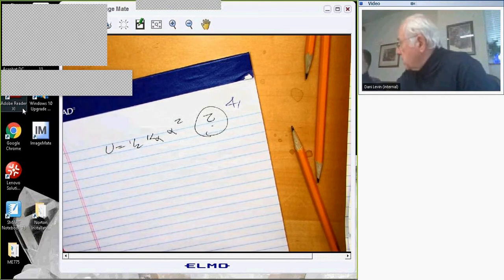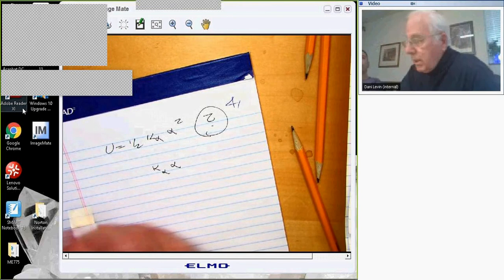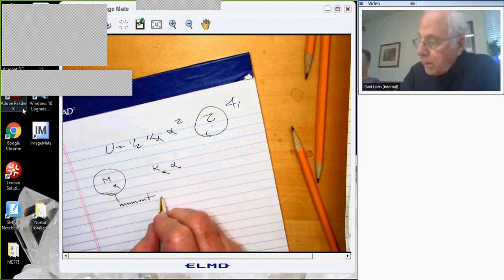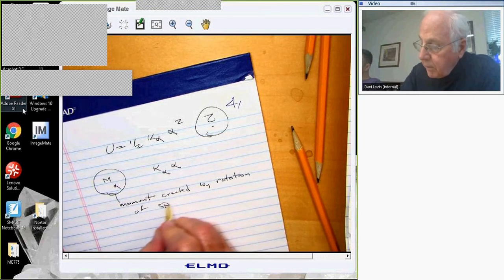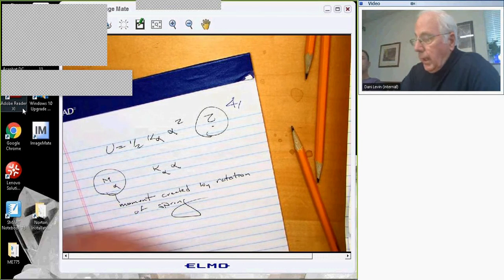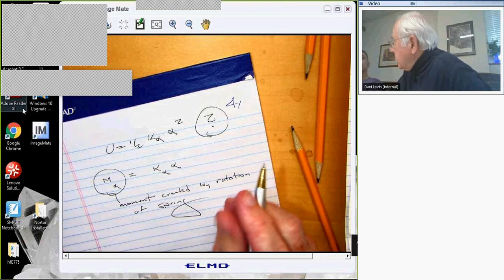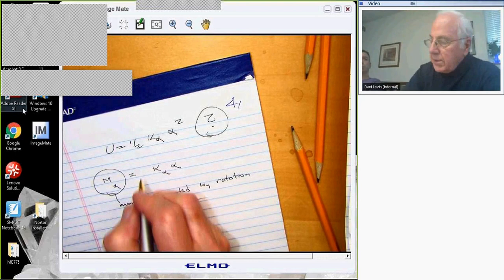the spring also rotates, right? Then there's a moment, which, according to a linear spring, this is M sub alpha. This is the moment created by rotation of the spring, and that's equal to K alpha times alpha, except we do have to think about the plus or minus sign. This moment is resisting the deformation, it's the nature of an elastic spring. So if I rotate the flat plate, the torsional spring deforms in a certain direction, then the moment is in the opposite direction, right? So we're going to put a minus sign here.